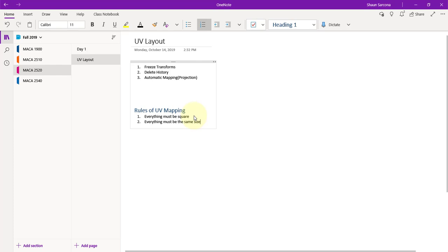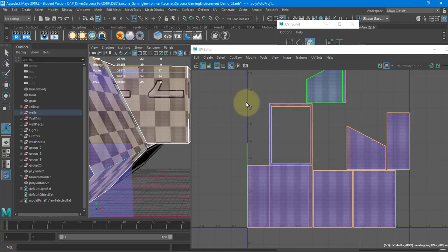So when we see those squares, think of those as our resolution. The tinier the squares are, the more pixels we can fit in there, the more resolution we can add. The bigger they are, the less resolution we can add, okay? Now, when we get into Substance and we're creating textures, we can adjust the size, but we never want to go crazy with the size of this file just so that we can get a lot of detail when there's stuff we can do inside Maya to not do that, okay?